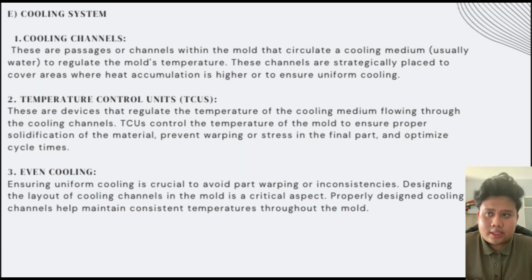Cooling system. First is cooling channel. These are passages or channels within the mold that circulate a cooling medium, usually water, to regulate the mold temperature. These channels are strategically placed to cover areas where heat accumulation is higher or to ensure uniform cooling.